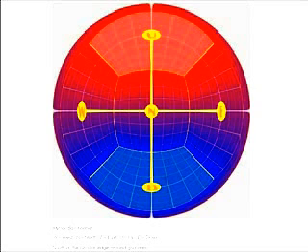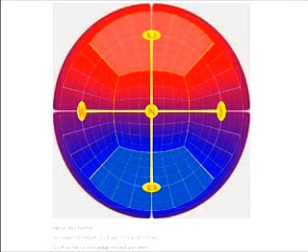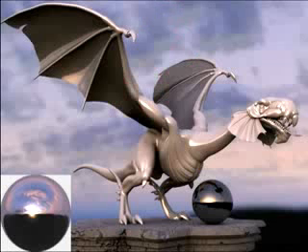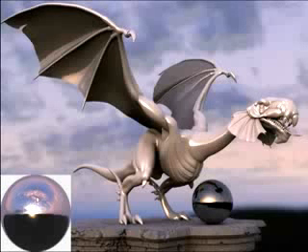The next thing I want to address, and a very important note of that, is the orientation of all these HDRIs. In their default orientation, the parts of each HDRI that represents the sky, or at least the area above the horizon line, is reflected in the top half of objects in a scene. And I was talking about this a moment ago, but I want to talk about it in more depth since I need to explain the controls in the material editor that allow you to change the orientation of HDRIs.